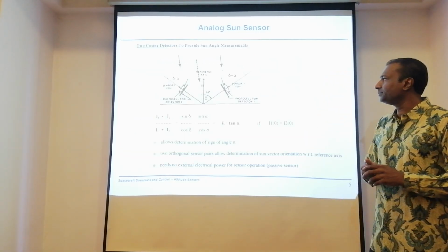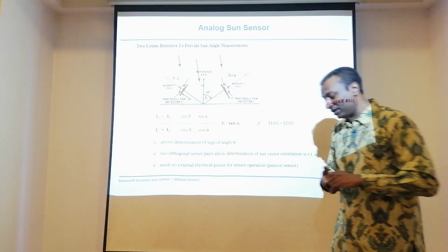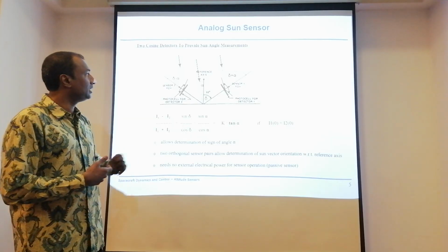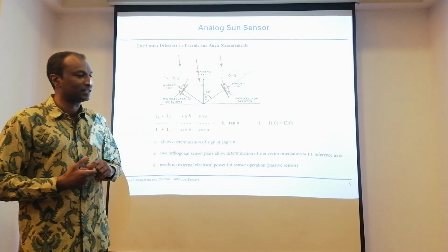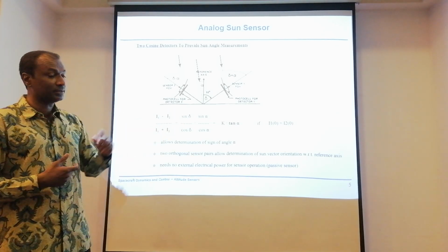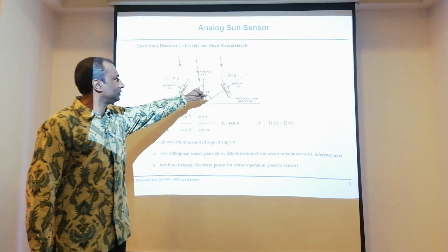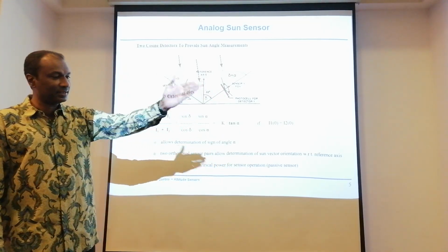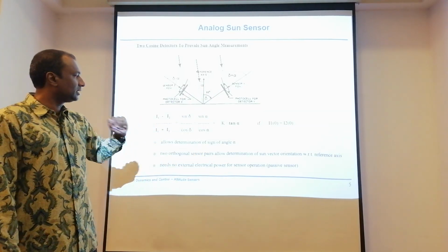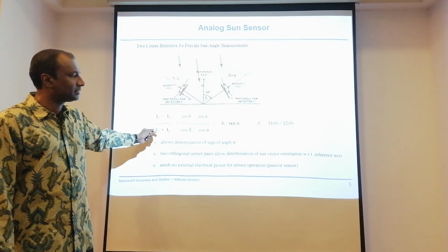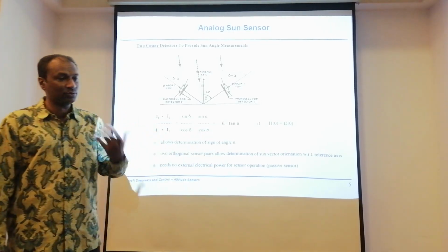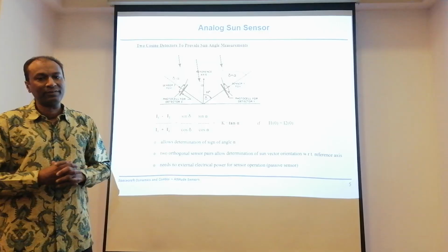Having one, you can't do much. Probably having two, we can do slightly better. Yes, indeed. If you have two of those photocells, just like what you see here, then we should be able to calculate the actual angle, that means where you are exactly heading. It's a very simple calculation, I being the intensity. Now the K value has to be calibrated. Once the K value is calibrated, the manufacturer will give it, and the alpha angle can be calculated.